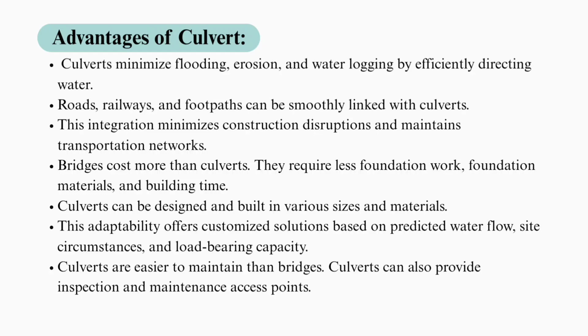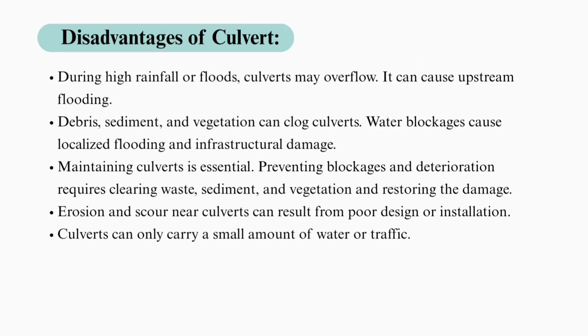Then the next point is that bridges cost more than culverts, because culverts require less foundation work, foundation materials, and building time. The next is that culverts can be designed and built in various sizes and materials, and because of this adaptability we can offer customized solutions based on the predicted water flow, site circumstances, and load bearing capacity. Culverts are easier to maintain than bridges, and culverts can also provide inspection and maintenance access points.